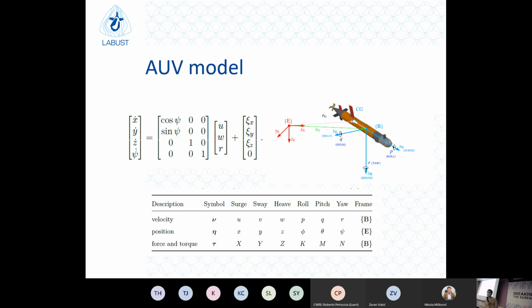Yeah, walls. They're bouncing off the walls, sound waves, and we refuse those measurements because using our position, we know the beacon position, right? We know approximately how long the range should be, and if it's over a certain limit, we just say no, that's acoustic error. Good, thanks.